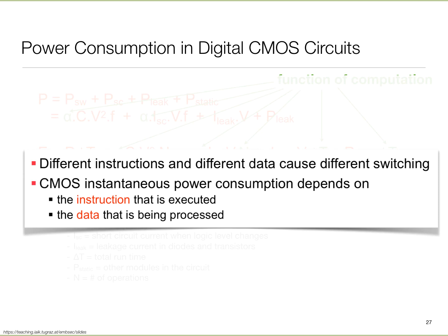In the case of CMOS, what that effectively means is that power consumption does depend upon the instruction that is being executed and the data that is being processed. If I examine the power consumption while the processor is doing an add or a multiply or a register move, they'll look different. Moreover, a multiply of two arbitrary numbers versus a multiply with 0 might look different. It depends on the processor. Some processors have more uniformity, some show more distinctiveness, but at a high level this is largely true, provided you are able to examine with sufficient resolution.